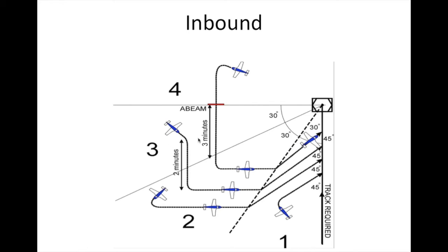Let's say I'm in section 3, flying in any direction, and I'm instructed by ATC to intercept radial 180 inbound. Okay, I know that I am higher than 60 degrees. I'll fly opposite of it, which is 180. I'm going to fly straight south until I'm 60 degrees away. Once I'm within 60 degrees or so, I'm going to turn perpendicular to it. I'm going to turn 90 degrees left, and then I'm going to continue until I'm 30 degrees from that radial, and then I'm going to turn 45 degrees to intercept it.